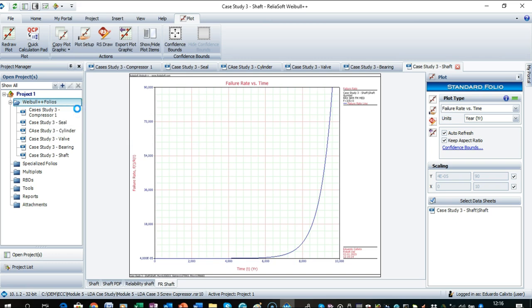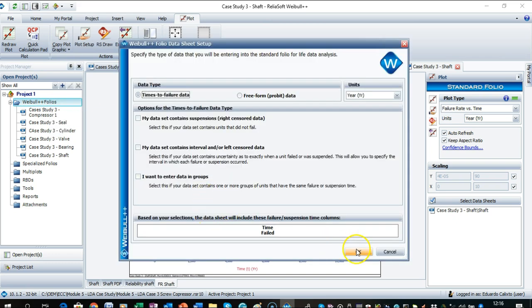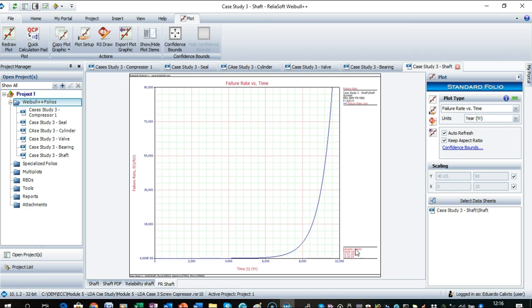That is also compressor 2. So we now create compressor 2, but compressor 2 will get the information from all these PDFs here, and we compare both. This time we are not repeating the mistake that we made before: just not looking at the components. That is what happens if in our database we do not have definition at component level, just look at equipment level, and get an interval between the failures at equipment level.